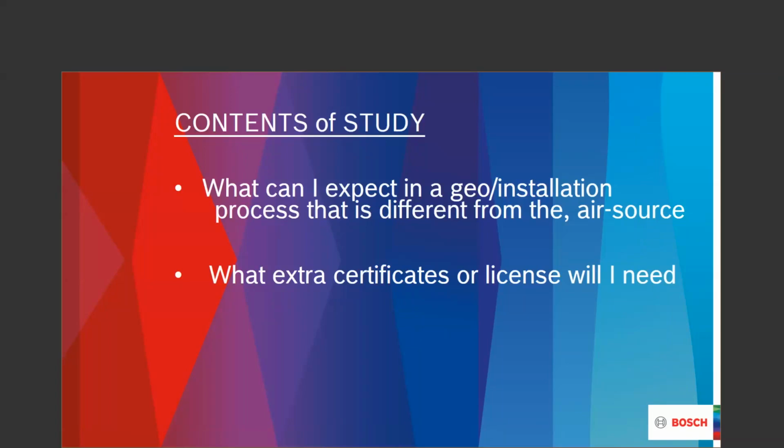Sometimes that goes into play. I know here in Oklahoma, we would call Okie Dig. And you basically can't put a tooth in the ground until 72 hours later. So the locators, the gas line, the telephone lines, the trunk people that come through the land with gas piping and all that kind of thing, they have their own people to come out and locate those items for you and flag them so that you can dig in a safe environment.